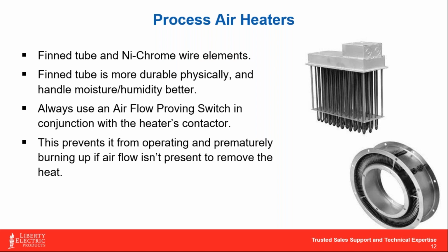An open coil heater looks like the inside of your toaster oven. If you've ever looked down into your toaster oven while it's running, you see those orange-hot elements that almost look like wires cutting across. Open coil elements are basically nichrome wires that are usually connected with ceramic discs because the ceramic can take the heat. They're usually less expensive to produce, and they are very effective. They last a very long time as well, but they don't do well in high humidity or moisture applications, where you get some arcing going on inside if it takes in too much humid air.